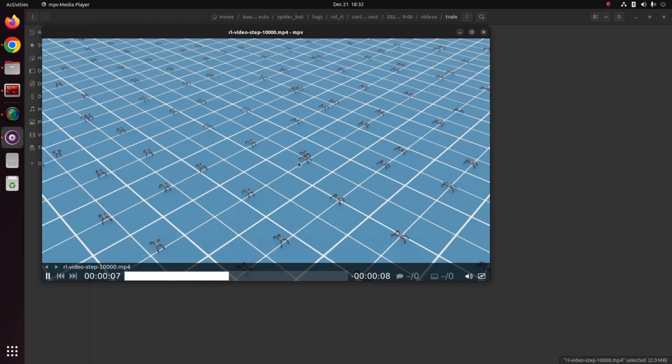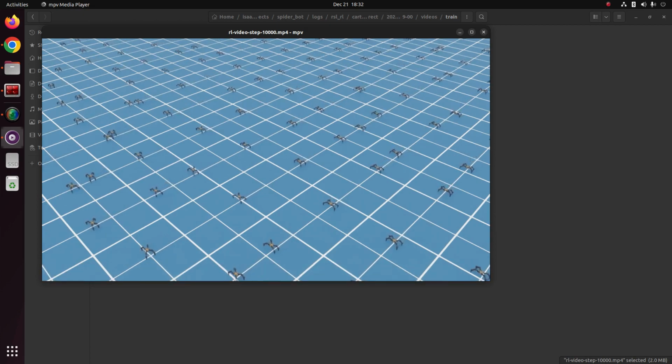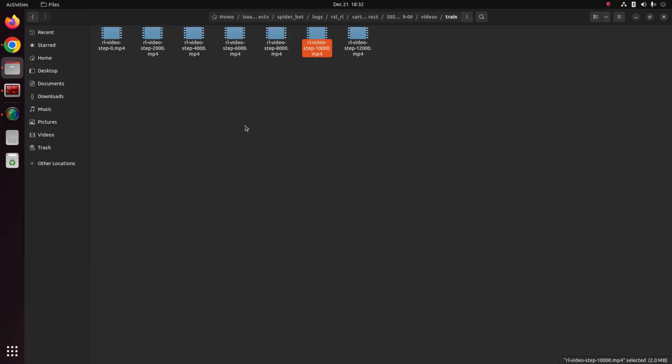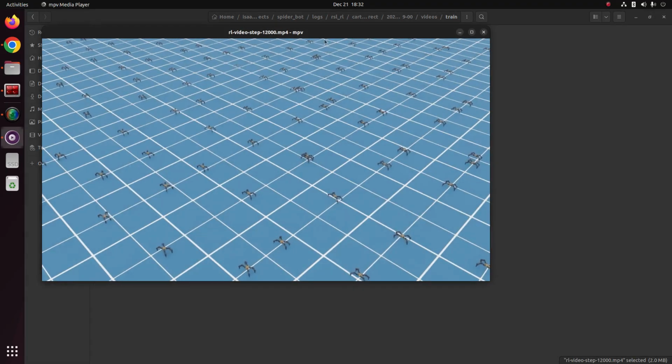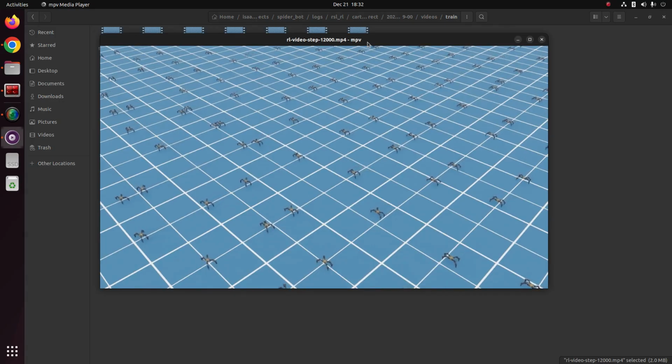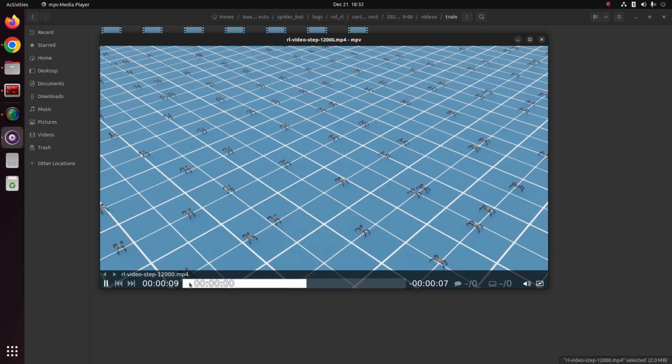It only took about 10 minutes to train this, and the main idea is that with very few reward terms, we can actually train it by just giving it a base animation to track, and the robot model will learn how to output good joint trajectories while also following the other commands.